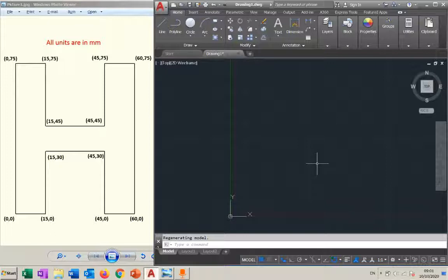Now if I start, we can click on line. I can type 0, 0, hit enter, then hashtag 0, 75, hit enter. Look, I can see what I'm drawing. Why? Because I use limit, and the limit basically brings a small area that the drawing will fit into. This is the idea of a limit. We said that even without limit I could see it. Yes, I drew something, then I zoom in, I start, and I continue the drawing afterward.